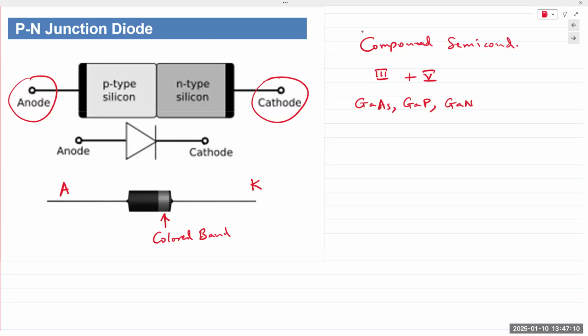Also, gallium arsenide is a compound semiconductor that dissipates energy in the form of heat and in the form of light, from which you get light emitting diodes or LEDs. Depending on the dopant impurity that you introduce into the gallium arsenide material, the wavelength of the emission is different, and hence you get different colored LED lights.